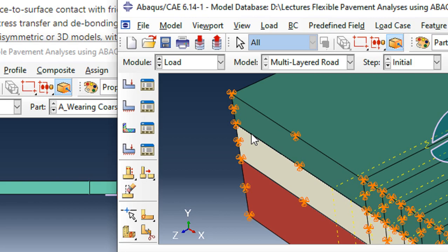Even if assigning different material properties to each layer and meshing them appropriately works for you, maybe using axisymmetric or 3D elements actually depends on the problem. For dynamic loads like traffic, dynamic analysis will have a different meshing approach for layers, and similarly elastic and static analysis will have a different approach. So for each layering system, the properties will affect your simulation.